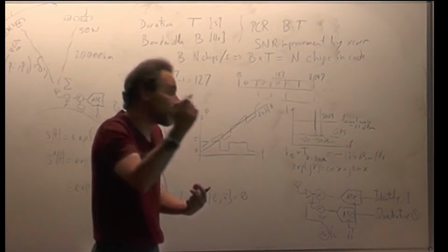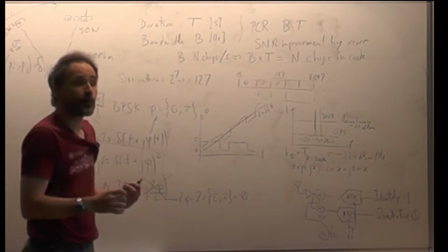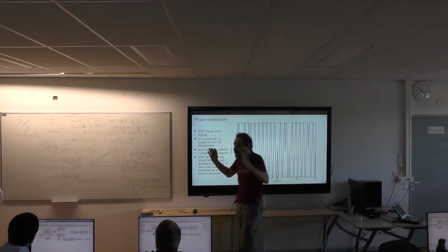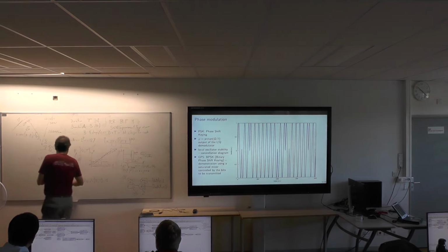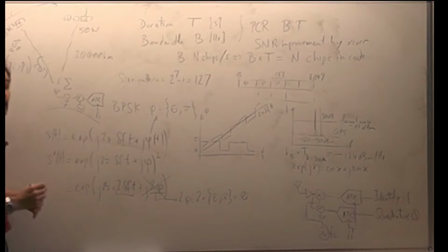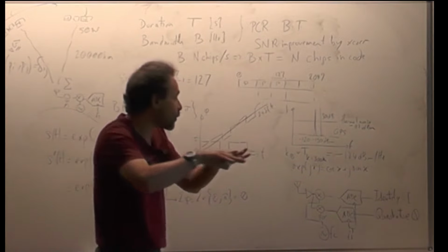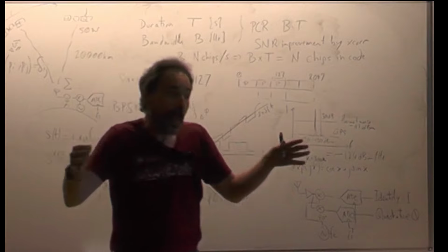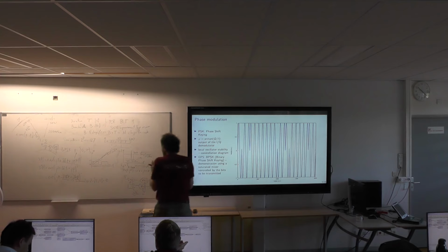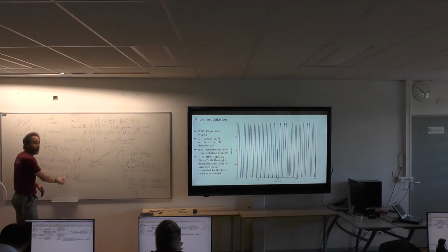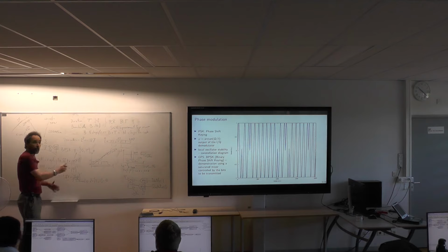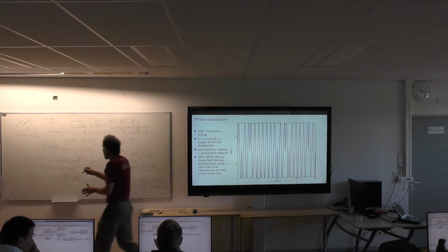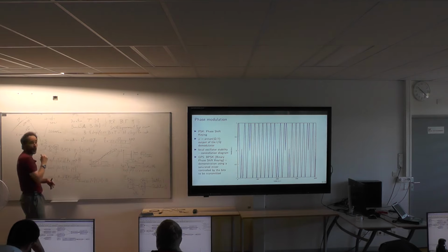So by squaring the signal, you cancel the phase modulation. But through energy conservation, where did the energy go? We collapsed all the energy into a carrier, a pure sine wave, at 2 times delta F. We used to have information that was spread over 2 megahertz. Your GPS signal is spread over a bandwidth of 2 megahertz. And by taking the square of the signal, you see that we accumulate all the energy in a pure carrier, and this pure carrier is at 2 times delta F. So if you take the Fourier transform, you see 2 times delta F, you divide by 2, you get delta F, and you can cancel out this delta F t and only keep the phase.